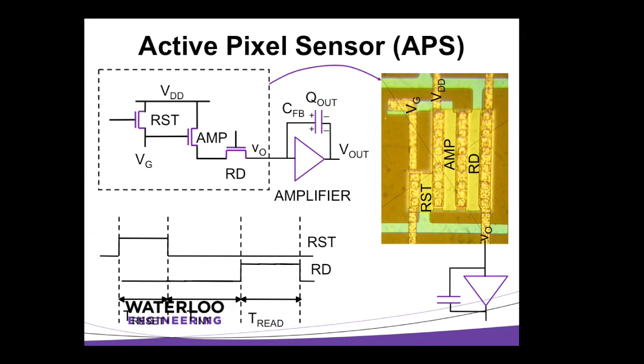There's lots of traps in it. There's problems with mobility. It's about 1,000 times slower than, say, silicon. And the lifetime of carriers is minimal as well. Okay? So when somebody comes along and says, let's build an amplifier, an analog circuit, in amorphous silicon, it's a little bit unusual. But this is what we tried. The biggest challenge we ran into with amorphous materials in building an amplifier was not so much the gain.